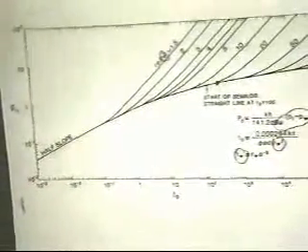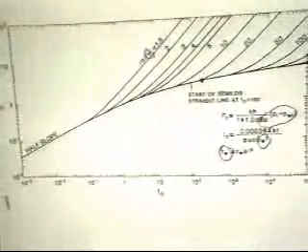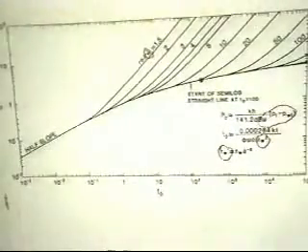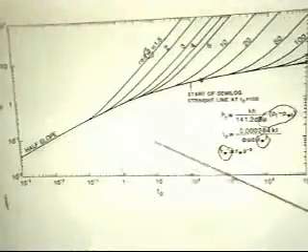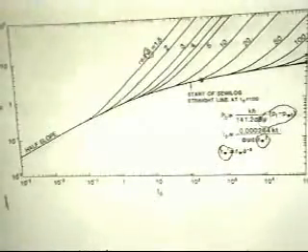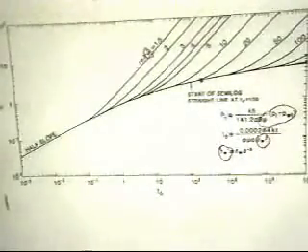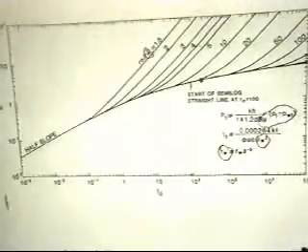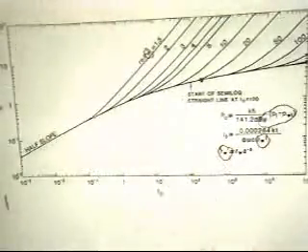This is what we call a type curve plot for the constant wellbore pressure solution that's used in drawdown and buildup analysis to get KH and skin, the pressure buildup approach to reservoir engineering. It's defined in terms of a dimensionless pressure and a dimensionless time. If you plot your data on log-log paper, the same scale, you should be able to move the data around on this plot until it matches somewhere along this curve.